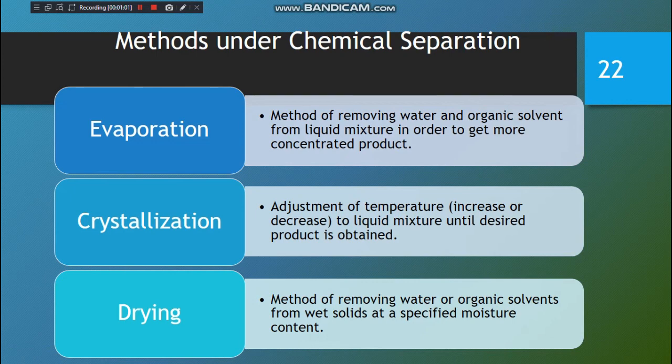And some books also state that an evaporator may be considered as a liquid dryer or concentrator that separates solvent from a solution by the evaporation process. In most cases, the solvent is water. Okay, so evaporation as a separation process is distinct from distillation. It is different from distillation in that the solute is non-volatile and a high degree of separation can be achieved in one stage only.